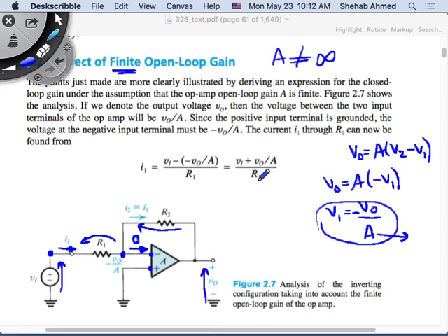Then, what is my objective? Now I can calculate the voltage drop here, right? The voltage drop here is equal to what? I input, or I1, times R2. This is this voltage drop. V output plus this voltage drop plus this voltage is a loop, right? This is a voltage with respect to ground. I have this current that is going to flow in here, and then it's going to flow through this resistor.